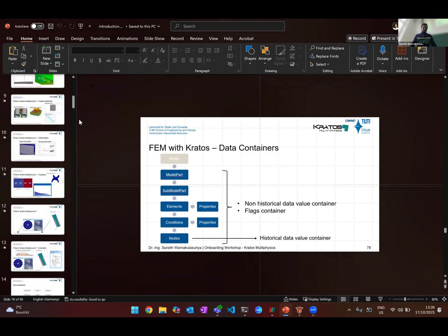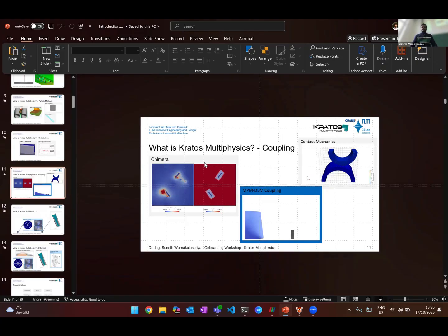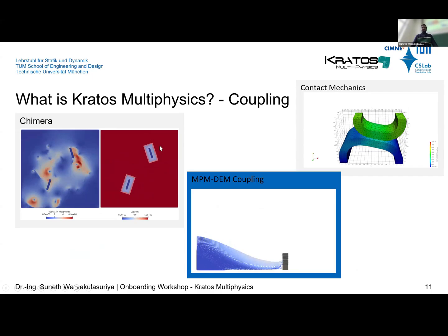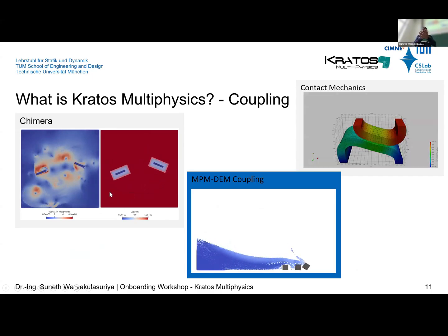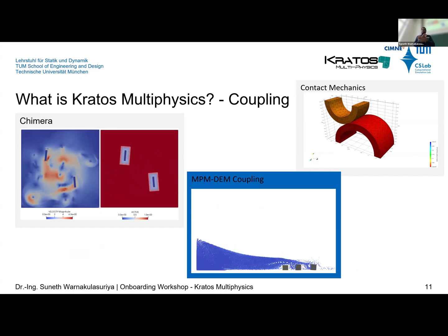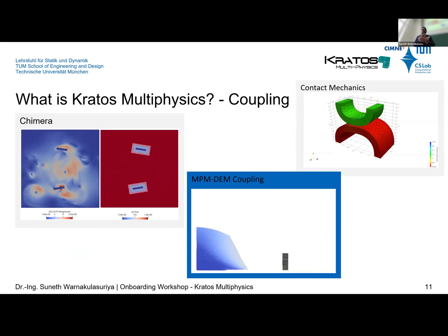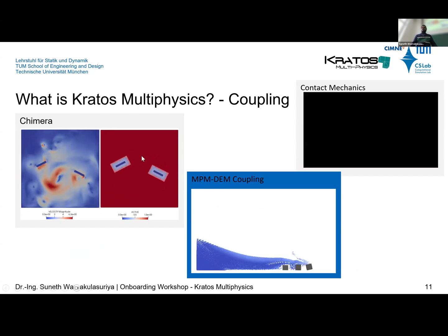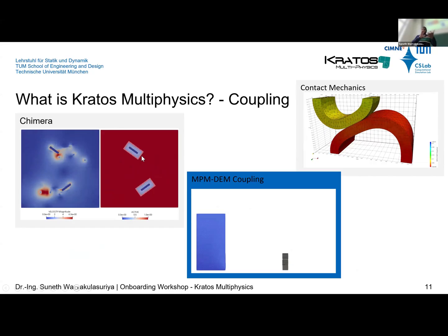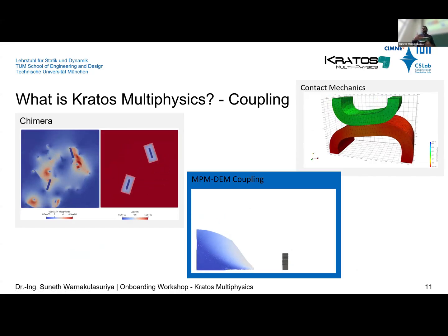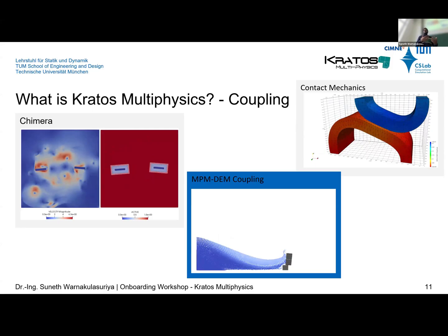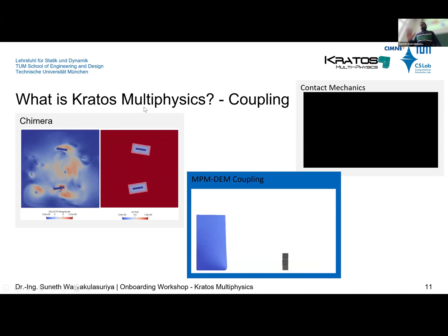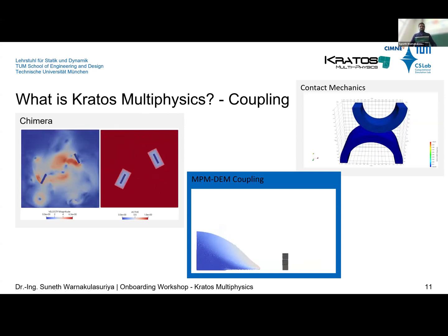I can show you again. Yeah, this one. So these two rotating things. Here you see this is one mesh and there's a background mesh. So this maps two overlapping meshes. In there, what we basically do is activate and deactivate elements, because one mesh is solid and the other one is fluid. Whenever you have a common area, you activate one of the physics. So to be fast and do that efficiently, we use these flags. This is only one use case, not the only use case.